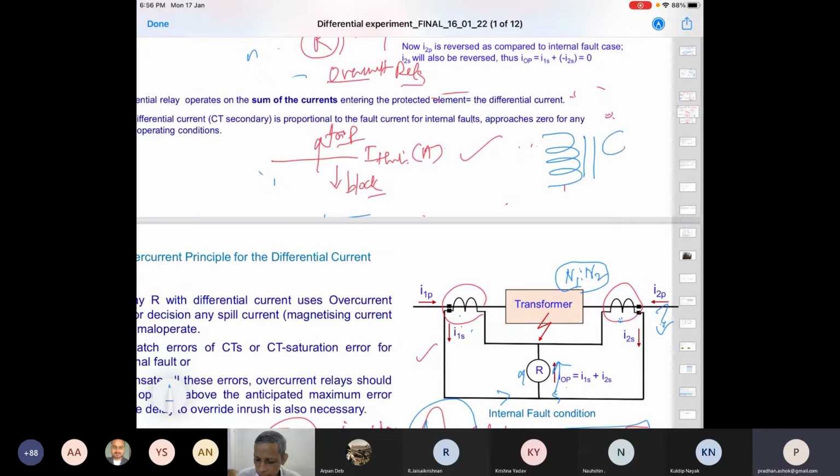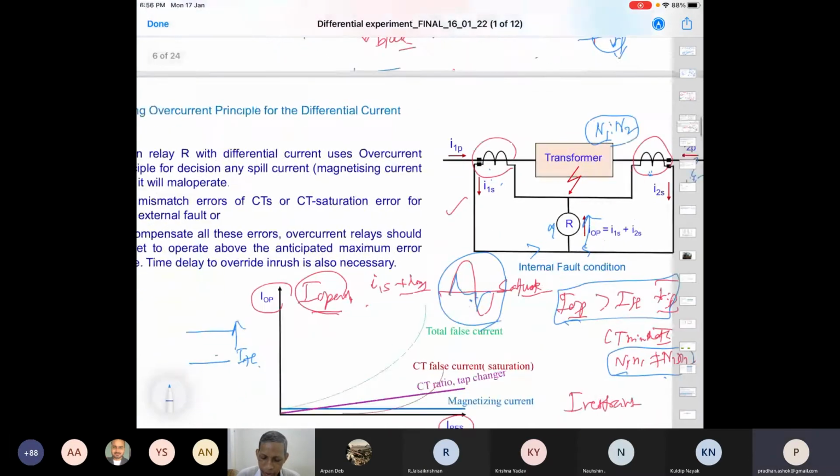If a fault happens to be towards the lower part of the winding, the voltage associated is smaller, and the current to the fault path will be smaller. If the fault happens to be in the upper portion of the winding towards the input side, then the path will be very limited and the current will be very, very large. So the lower level of current may not be detected by this threshold because it may be lower than this.